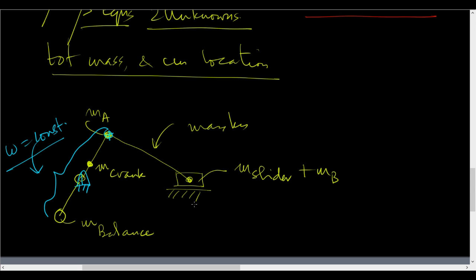When that happens, I still have the acceleration of this one, which is required to be achieved, and for that there are forces from the frame. All right. And as we have discussed, to a reasonable approximation, that is just the horizontal part of the acceleration of this point, right? Because the position of this has the same variation as the horizontal component of this. Okay. So this will cause vibrations in the engine frame.